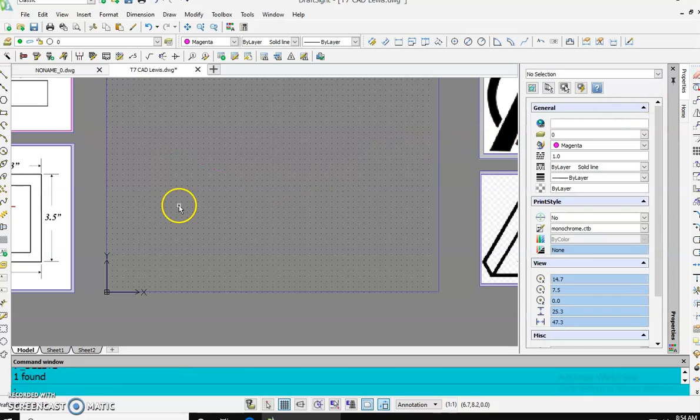Now, anything on the left side of the screen is a drawing command. So you have line, you have an infinite line, you have a rectangle, you have polylines, arcs, circles, etc. Some of these you're going to use, some of them you may not touch at all. One of the things we're also going to use is this button right here called Hatch and Fill. That's going to add color and depth. That's a fun one to use. And again, understanding what the icons mean and what they do is really important.